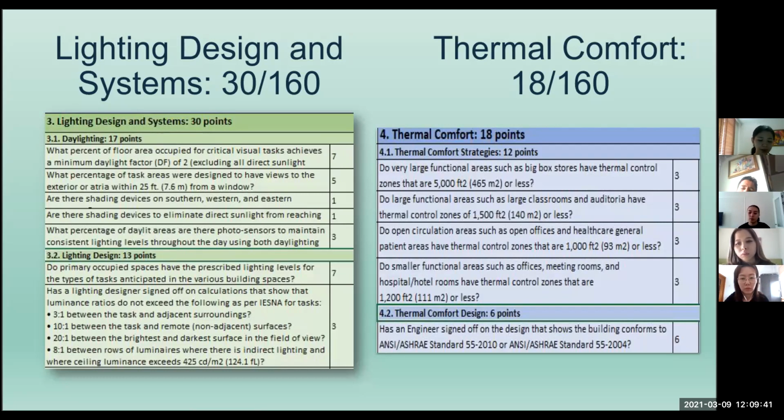It includes such parameters as daylight factor, so that human occupants are met with an adequate level of sun exposure. However, excess exposure is not good for human health too, and it also includes parameters such as the presence of shading devices such as curtains or something similar. And lighting design is mostly about the light obtained from the luminaire, or simply saying from the electricity. And it includes the presence of the minimum lighting level requirements.